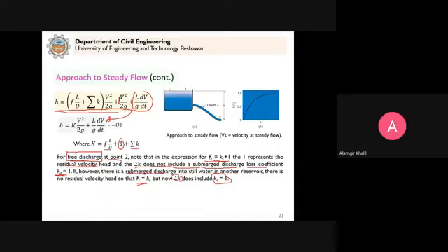So it means that whether we have free discharge or submerged discharge, essentially it is the same. Either the 1 is here or this K_D is here. Essentially the same. So there is no problem whether at point 2 we have free discharge or submerged discharge. We get the same answer. If, however, we neglect the minor losses, then this is a residual head, not a minor loss, so you have to consider this. The situation will be different if we ignore the minor losses in a problem.